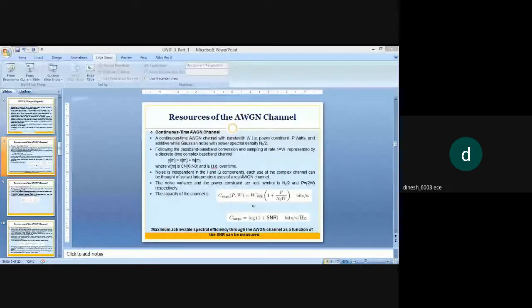where Shannon capacity is generally used as an upper bound on the data rates that can be achieved under real system constraints. At the time Shannon developed this theory of information, data rates over standard telephone lines were in the order of 100 bits per second. Then it was believed that Shannon capacity could predict a speed of roughly around 30 kilobits per second over the same telephone lines, which was not achieved in reality.